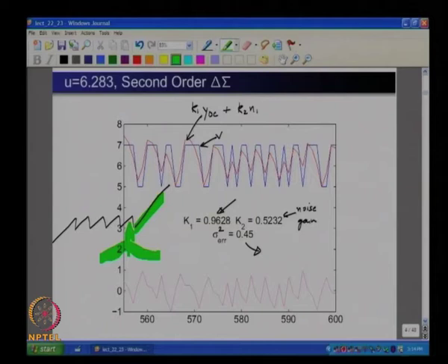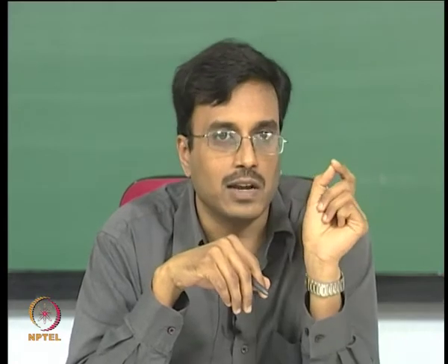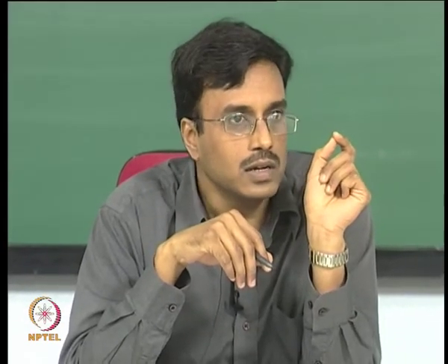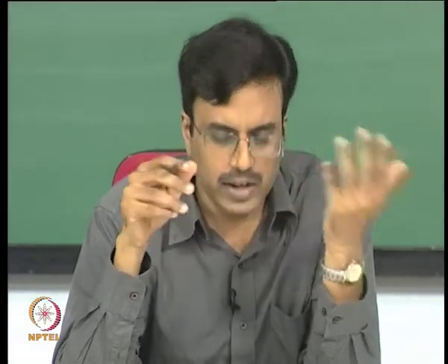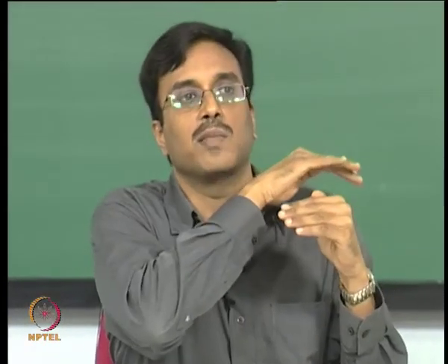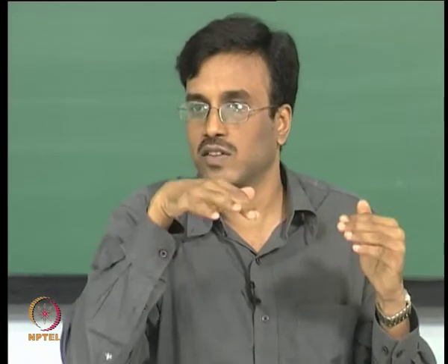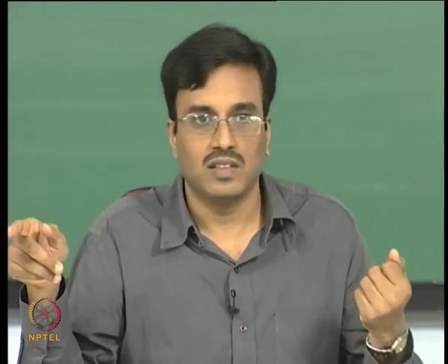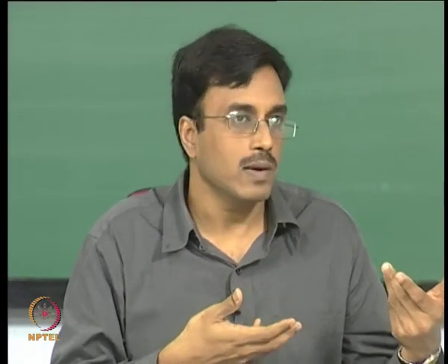But the key point is to notice that the noise gain has dropped, and dropped quite dramatically, correct. Intuitively this makes sense, because the noise is now saturating the quantizer, and when the quantizer is saturated, there is really no resemblance between the output waveform and the input waveform. So it is almost like the noise is not coming out at all, which in average terms means that the gain has come down. Does this make sense?